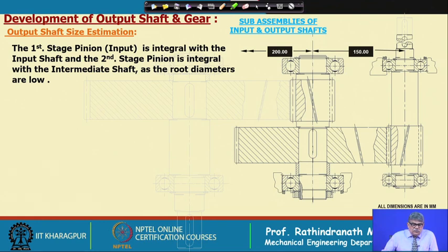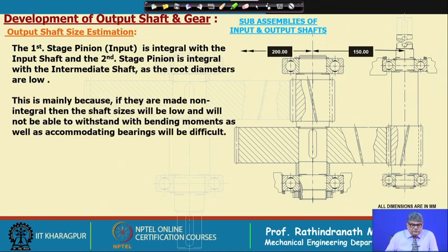In those two shafts, if the pinions are made separate from the shafts, then the shaft size will be so small that it may not be able to withstand the bending moment or even the torque there.